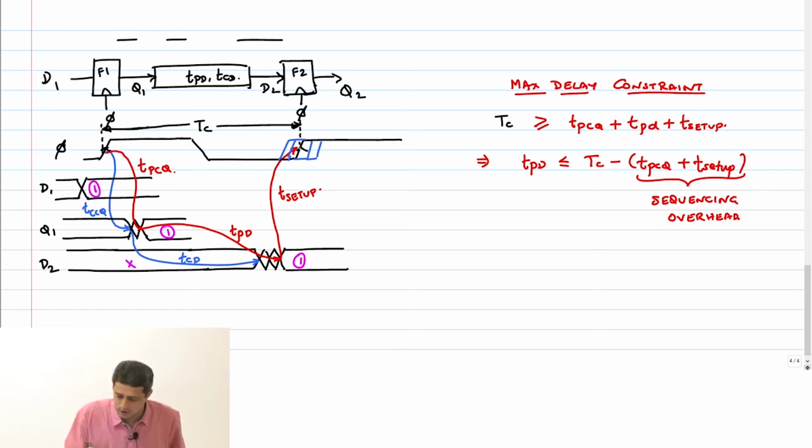Okay, so what is clock skew? What is the exact delay here? It's from the reference clock edge, where this thing moves, right? So for example, I have shown you a band of curves here, a family of curves. Clock skew is basically the worst case delay. What is the worst case offset that I can have? That is called clock skew.